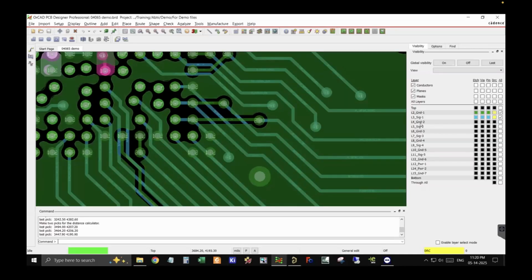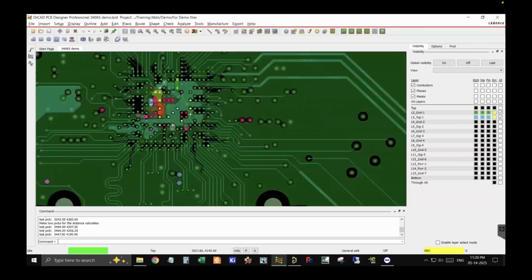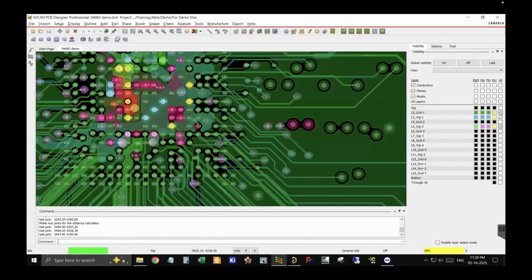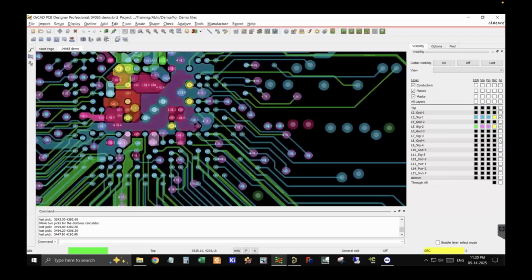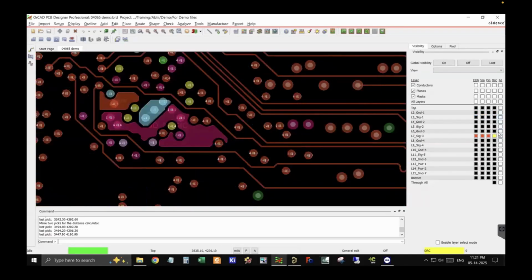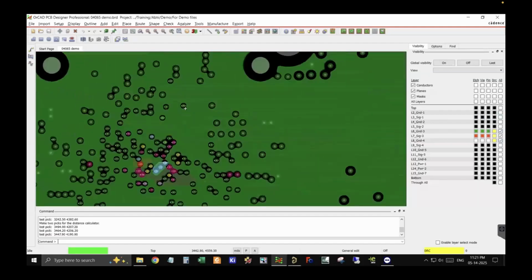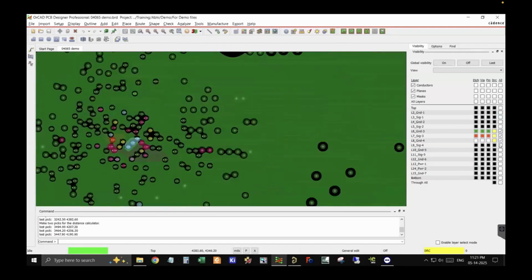So definitely there will be a lot of signal cuts in grounds, and the reference might not be clear, and the 70 ohm lines were very critical, so the reference had to be very tightly followed. So that was the reason layer 3 and 5 were not used. So we used layer 7, with copper on both the sides. So now here we have tightly followed the reference for layer 7.